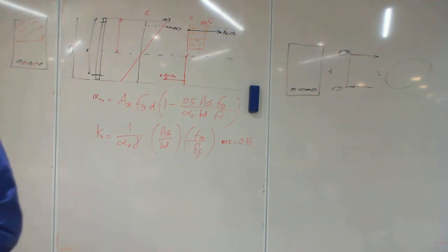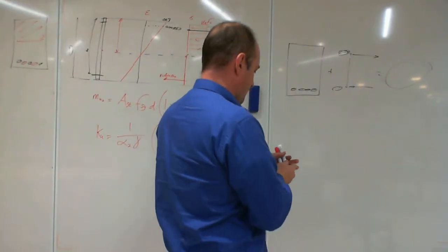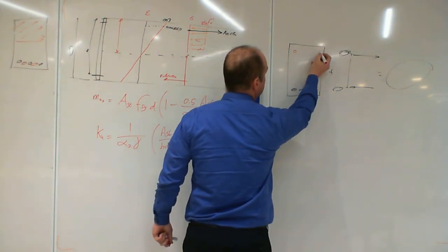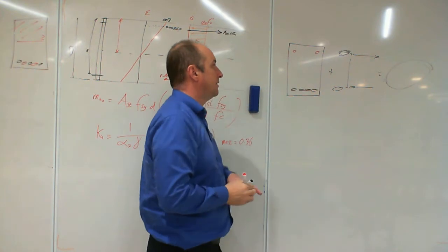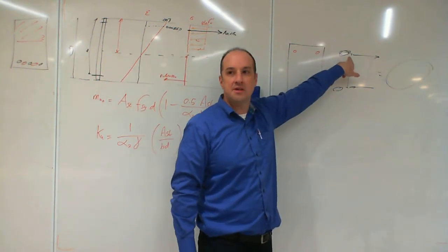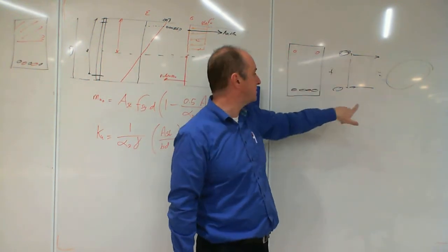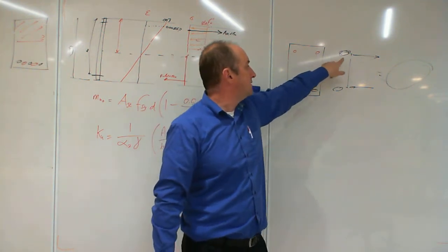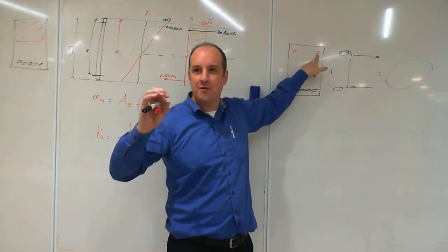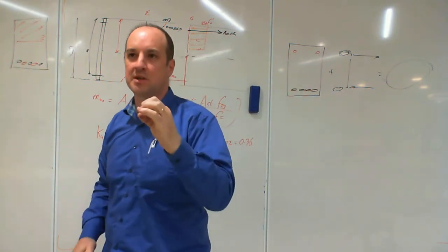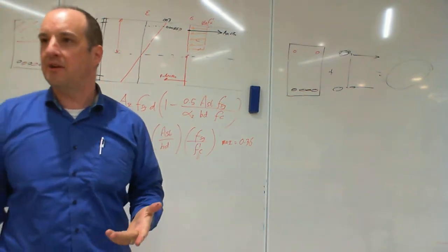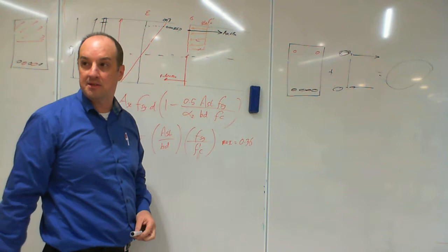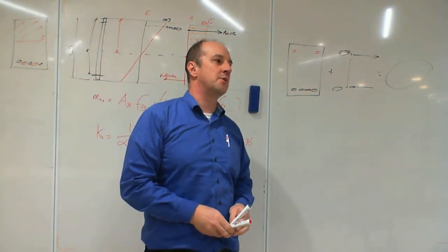Okay, the next complication. We've got steel there, and we've taken it out and using it for the steel beam. This is our primary beam, this is our secondary beam. Okay? That steel actually was taking up area of concrete. And although it seems quite small, it is significant enough to matter. Because there, concrete is missing a bit of area which is occupied by the steel. Okay? So we have to deal with that.